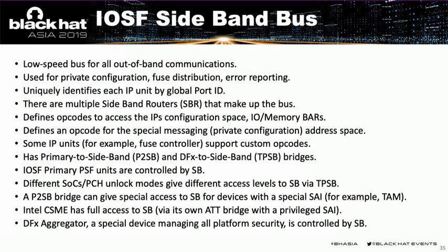Now about the IOSF sideband bus. It is a low-speed bus designed for all out-of-band communications, for tasks such as private configuration of devices, fuse distribution, or error reporting. If you have full access to the IOSF sideband bus, you can control the most part of a system. For example, you can interact with the fuse controller and do many other very interesting things.